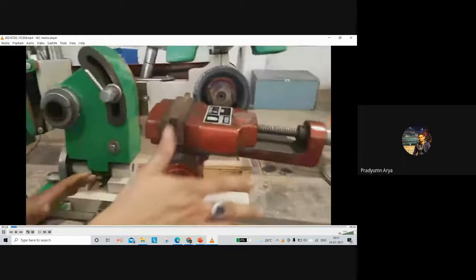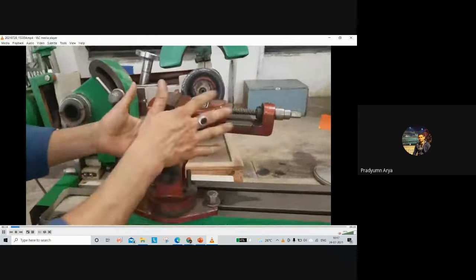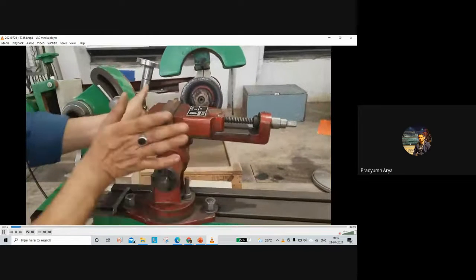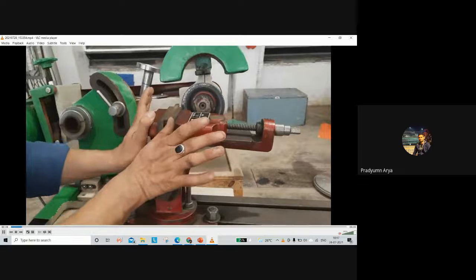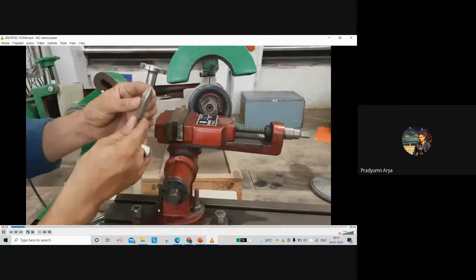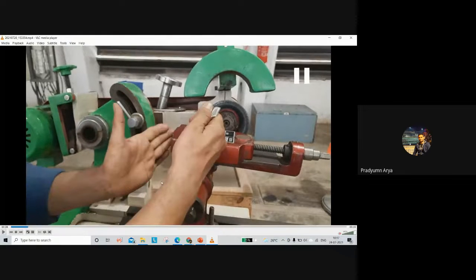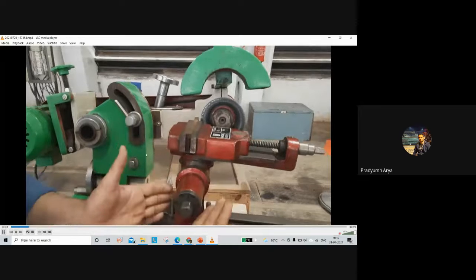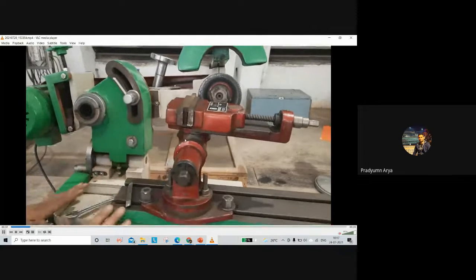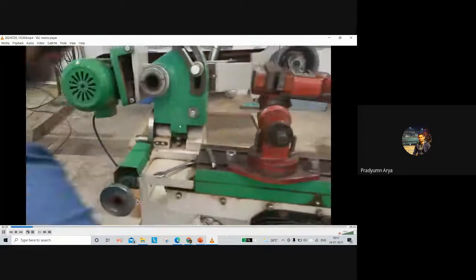Start with the universal vise. A vise with all degrees of freedom allows the workpiece to be set at any desired angle. The fully graduated 360 degree revolve base allows complete rotation along the vertical axis. And the third, the angular side with a moving axis, allows for any setting in the 3D plane.